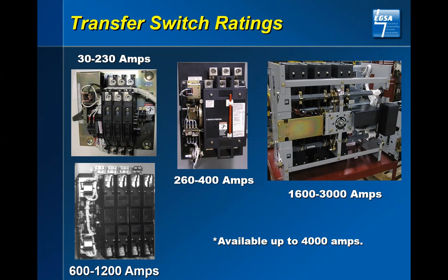The second point is that when you look at transfer switches, and if you are a person that is trying to put that transfer switch into a room, you need to look at every manufacturer that you may be allowing. If you're allowing ASCO, Russell, Zenith, Cummins, and such, you may have to look at it and see the ASCO switch, the Cummins switch may fit, the Russell Electric switch may not. You need to be aware of these breaks, and you need to be aware of the size differences and such.